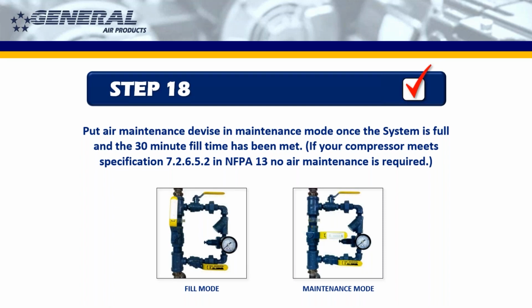You must open up all the valves. It will go through the entire AMD. It will fill up in 30 minutes. And then once you're at your 30-minute fill, close the fill line, and then all the air will be routed up and around through the regulator.